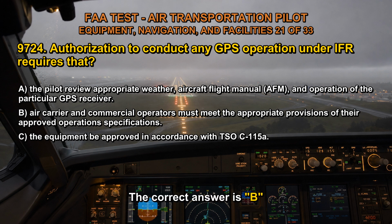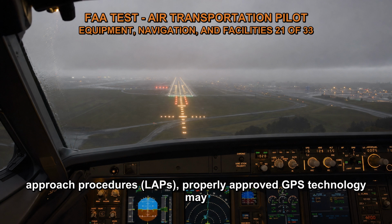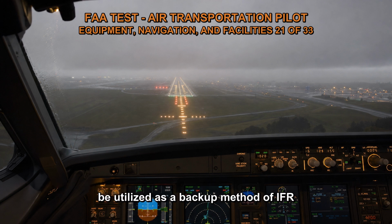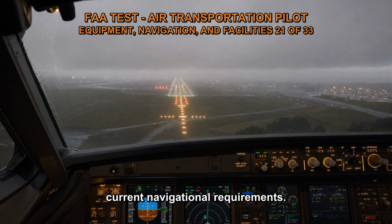The correct answer is B. For domestic en route, terminal operations, and some instrument approach procedures, IAPs, properly approved GPS technology may be utilized as a backup method of IFR navigation. This clearance enables the use of GPS in accordance with accepted air carrier operating guidelines and current navigational requirements.